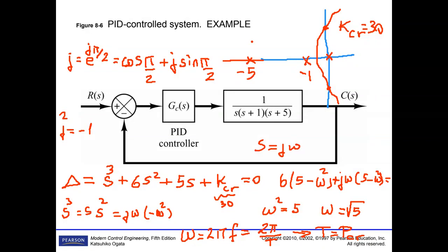Okay, nice. Let's go to our Bode diagram. What is a Bode diagram? It consists of two graphs. One plots the magnitude of the sinusoidal transfer function, and the other plots the phase angle. Both are plotted against frequency on a logarithmic scale.